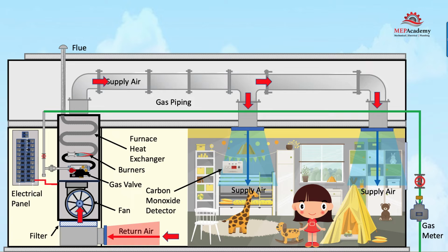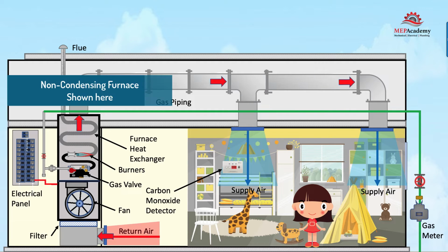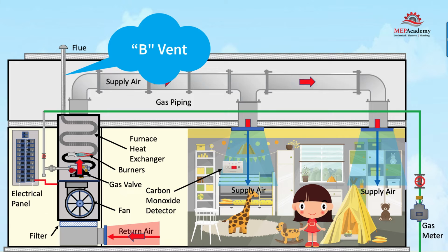Combustion and flue exhaust will need to be provided. With a condensing furnace, this is accomplished by installing a combustion inlet pipe to the outside, direct venting, or inside, non-direct venting, and a combustion flue exhaust to the outside. If using a condensing furnace, then vents can use 2-inch to 4-inch PVC, as the flue gas temperatures are much lower on these types of furnaces. For non-condensing atmospheric furnaces, it's common to use B-vent. Check the furnace manufacturer and local code authority for venting requirements.